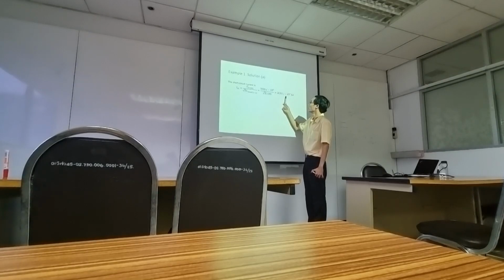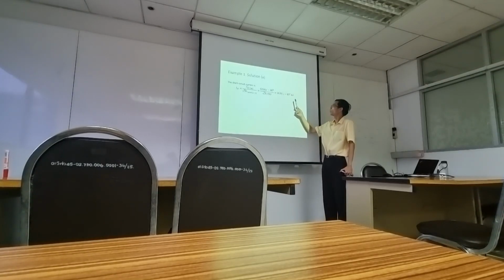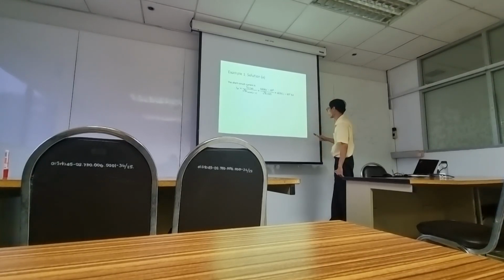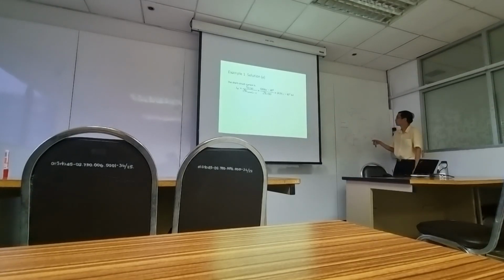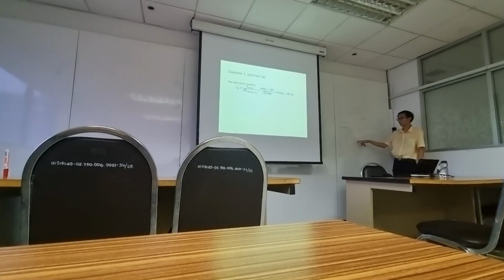So you will have 20.92 angle minus 85 degrees kilo amps. It means if there is a short circuit right here at the high voltage side of the transformer, the three-phase short circuit current would be around 21 kilo amps. Okay, any question?